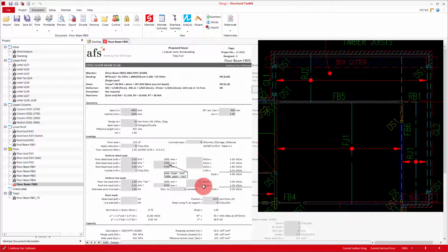When designing floor beams like this, you'll need to be constantly thinking about the different kinds of loads that may be on the beam. And so by setting up our drawings in the way we have, by including hatch for load bearing walls, and also showing any columns that come from above in their own color, we've made it quite easy to work out where all our loads go.